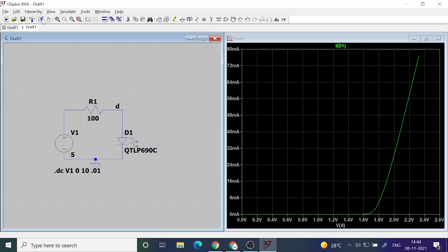Okay, gallium arsenide is one such material, and there are many other compound semiconductors which have this feature, and they don't require any momentum change while emitting light or absorbing light. Okay, so such materials are mostly used in making LEDs or even solar cells, direct band gap.